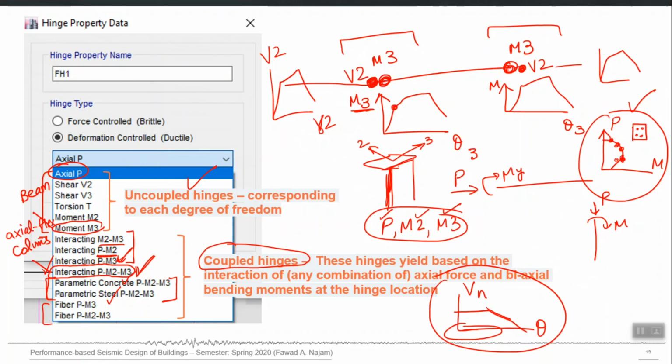This is called premature shear failure, right? Now if you have this kind of behavior input in your model, which is possible in Perform 3D, that model will be able to capture premature shear failure. ETABS will not even know this failure has occurred, right? Because it doesn't allow you to define such a detailed interaction between two actions. In this particular case, it is shear versus flexure, right?